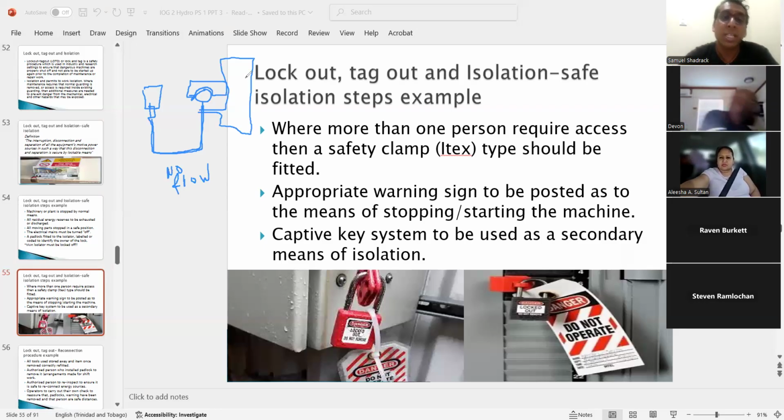But when the work is finished, if workers were cleaning this tank, corrosion resistant, you name it, paint in the tank, whatever, if they take out the key now and transfer the key here and open the valve, then oil or gas will start to flow here and come back here and prime up here. So when they turn this valve, the gas or the oil or the water would be right there, ready to fill into the tank. That's a captive key control system, right?